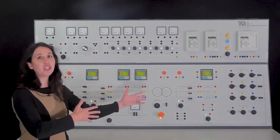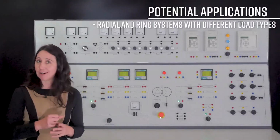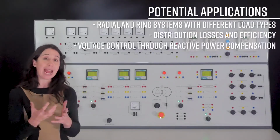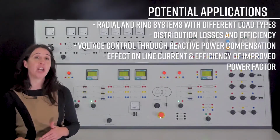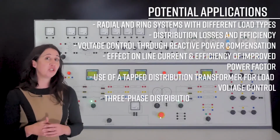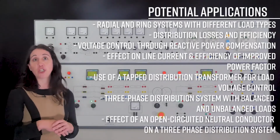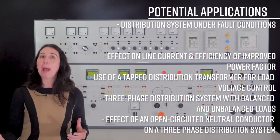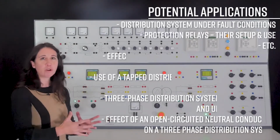To summarize, the Power Distribution Trainer allows you to learn in depth about radial and ring systems with different load types, distribution losses and efficiency, voltage control through reactive power compensation, effect on line current and efficiency of improved power factor, use of tap changing distribution transformer for load voltage control, 3-phase distribution system with balanced and unbalanced loads, effect of an open circuited neutral conductor on a 3-phase distribution system under fault conditions, and protection relays and their setup and use. There's a whole lot going on with this trainer.